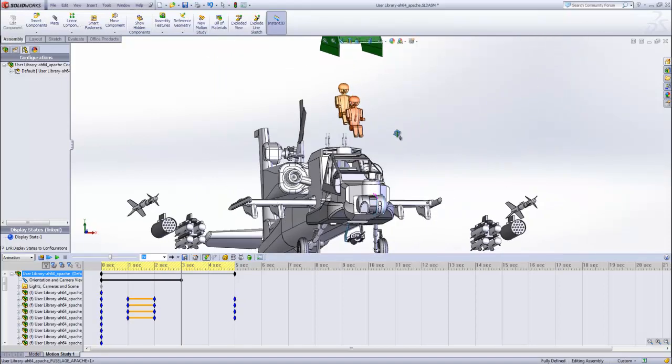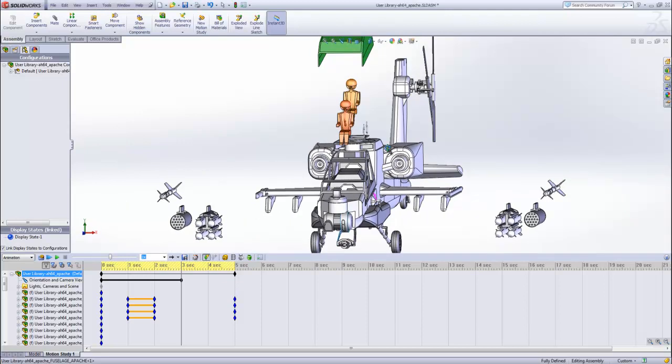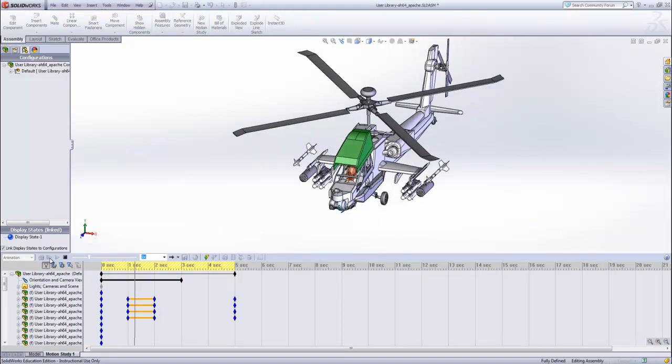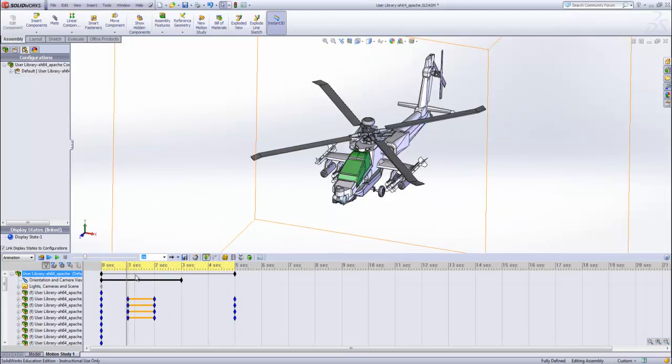Once finished, you can see that the timeline now contains a black bar from the beginning until the 3 second mark. This represents the camera angle changing from the initial position to the marked position over the 3 second time frame. This animation also includes when the object explodes at 2 seconds. We can manually select the points on the timeline to see how the object changes over time.